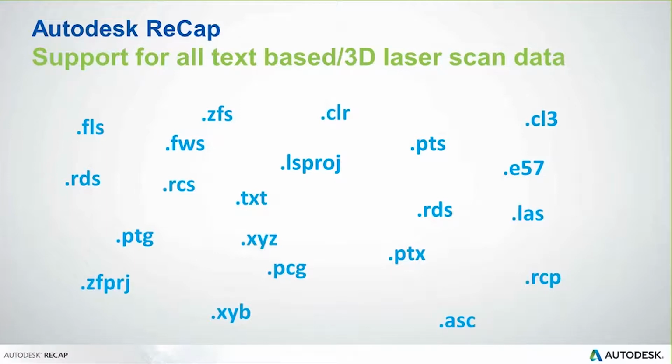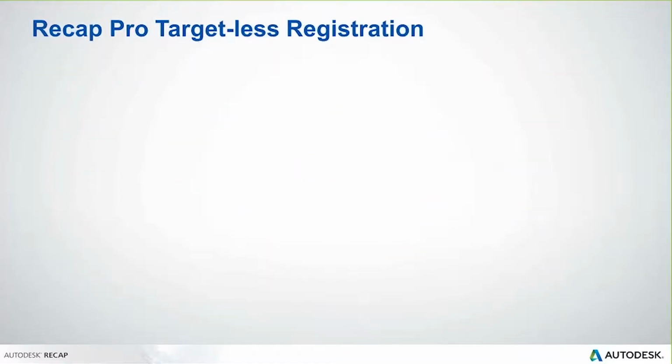formats. And the good news is that most of your scanners, no matter your manufacturer, will be able to at least export to this file format. This means that whether you've done the scan yourself or you're working with a third-party firm that is doing the scanning, they'll be able to provide Recap-ready files so that you can do your editing and cleaning up. And maybe it's not editing or cleaning up, but you want to section up part of your project. You can do that all within Recap. As long as you have this file format, Recap will consume it.